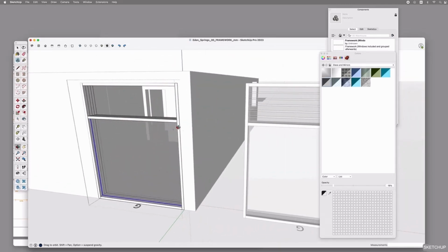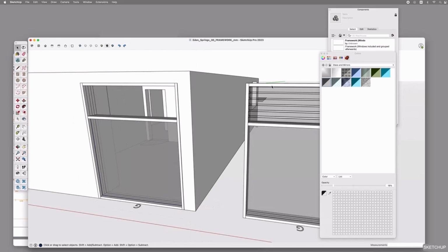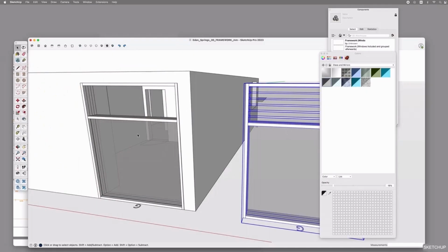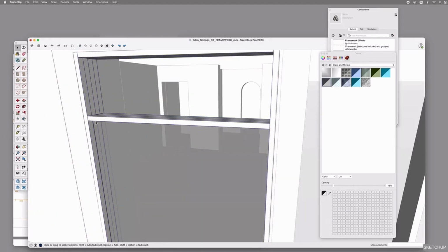So I didn't specify the Louvre panel height, but let's say it's 100 mm or 3.94 inches high. I could create it from scratch using my rectangle tool in the same way, but let's copy the panel we already have, as we won't need to push-pull it out and then apply the same material again.